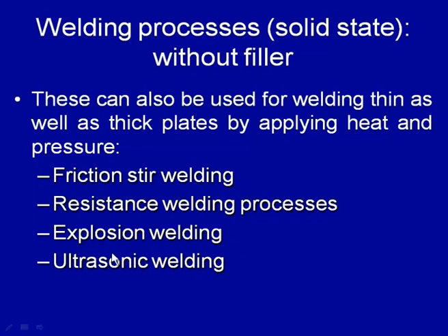In this process, the joint is mainly formed by mechanical interlocking at the interface, while in ultrasonic welding process the joint is obtained under very low temperature conditions without addition of filler material, and the required frictional heat is obtained by supplying ultrasonic vibrations at the interface through a suitable ultrasonic welding device, and that helps to generate minor frictional heat, at the same time leads to mechanical interlocking and diffusion at the interface to produce the weld joint.